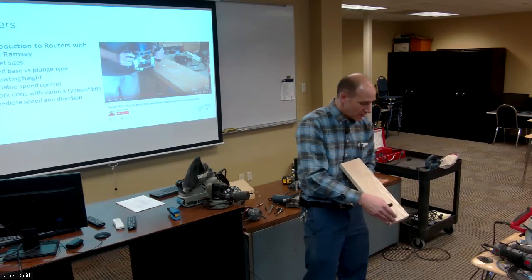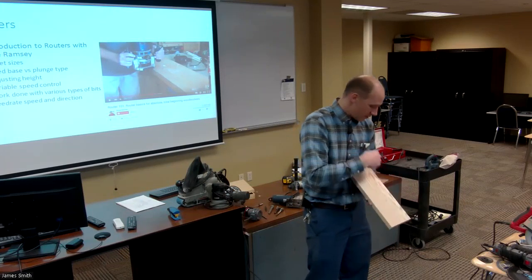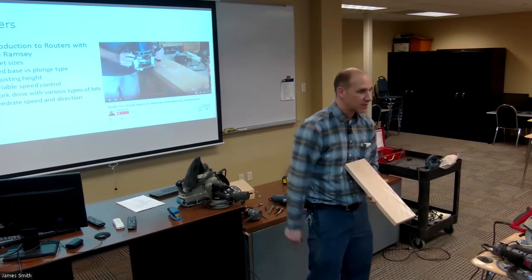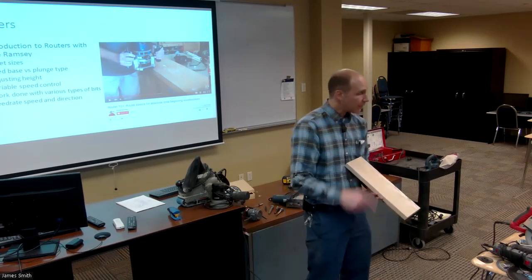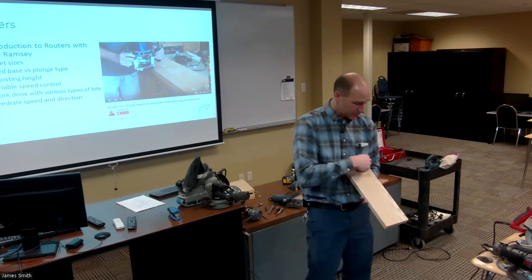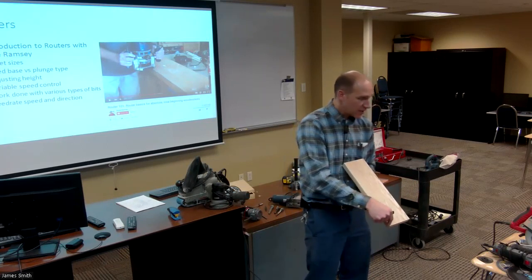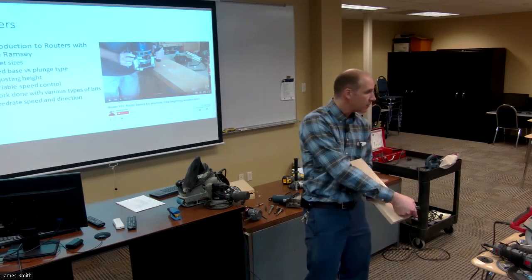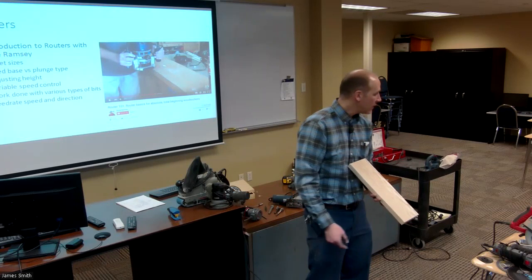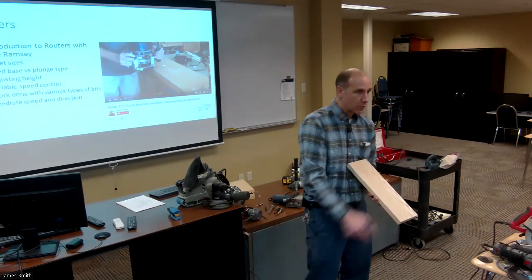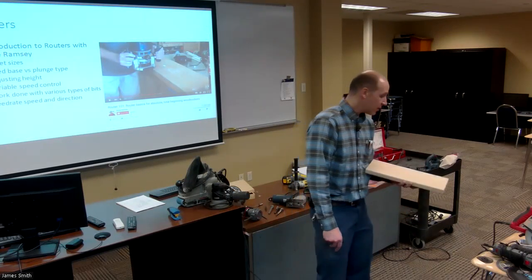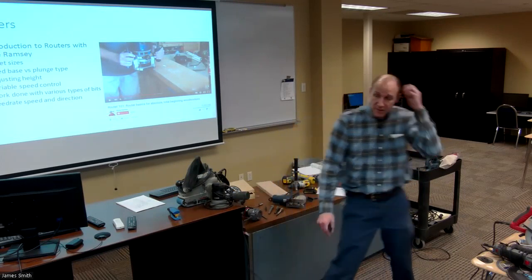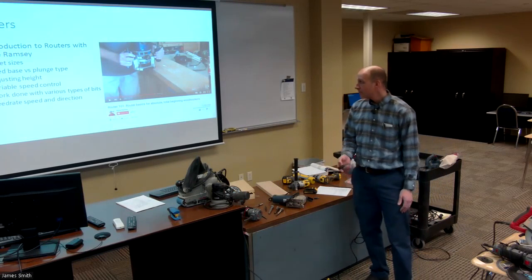And so if you do the end first, it's going to chip out, then you do the edge, and you've just removed that material. You don't see that it was even an issue. However, if you did the edge first, and then you did the end, it's going to chip out on the end, and now you've got this little bit of chipped out grain on the end, and nothing to remove, right? And so it does matter. Make sure that you always route the end grain first and then the edge grain, okay?